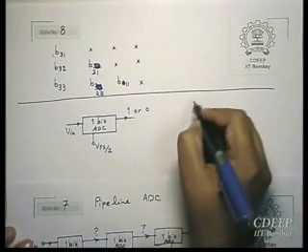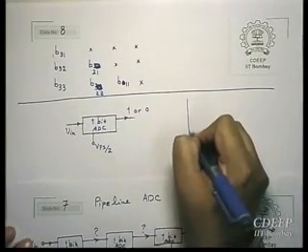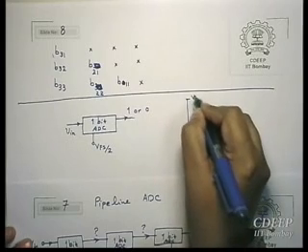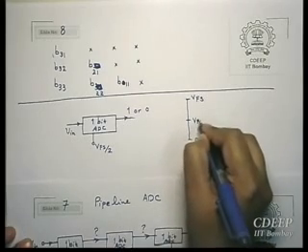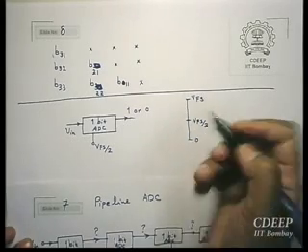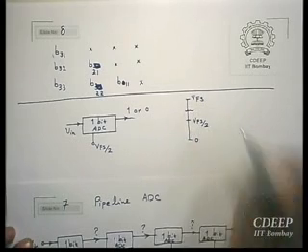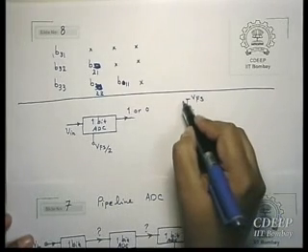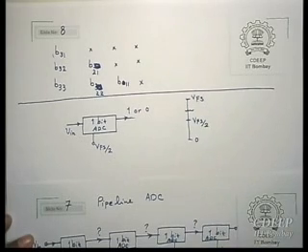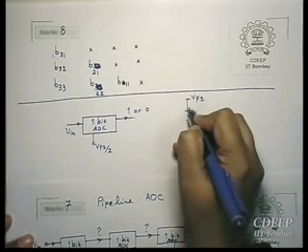So now, giving an example, suppose this is a 1 bit ADC, this is V full scale, 0, V full scale by 2. So you have a signal, for example, somewhere here. So the output of the 1 bit ADC will be 1. Fine. So now you know that your signal is somewhere here. But you want to have more resolution than 1 bit. Now what would be the next step?